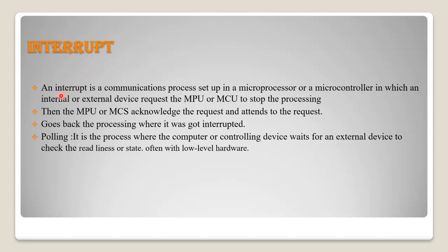Interrupt. An interrupt is a communications process set up in a microprocessor or microcontroller in which an internal or external device requests the MPU or MCU to stop the processing. Then the MPU or MCU acknowledges the request and attends to it, and goes back to the processing where it was